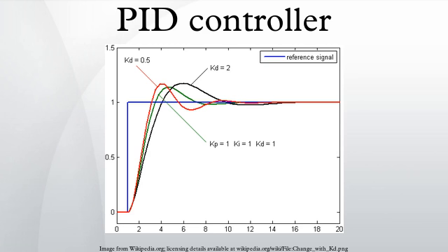This is achieved by setting the other parameters to 0. A PID controller will be called a PI, PD, P or I controller in the absence of the respective control actions. PI controllers are fairly common, since derivative action is sensitive to measurement noise, whereas the absence of an integral term may prevent the system from reaching its target value due to the control action.